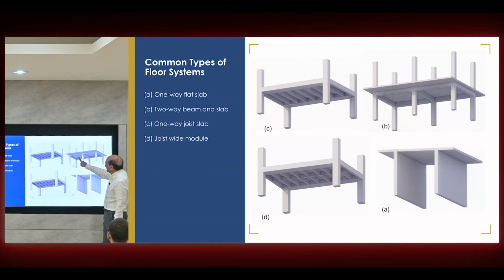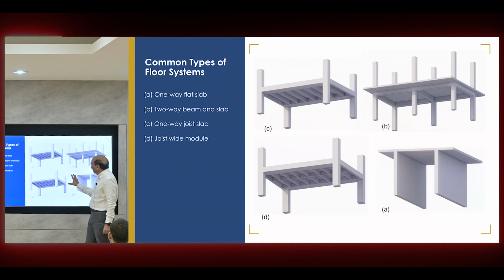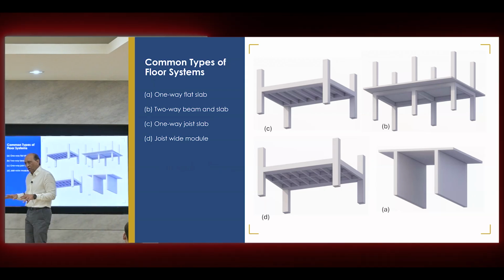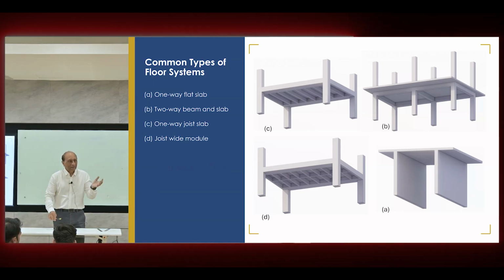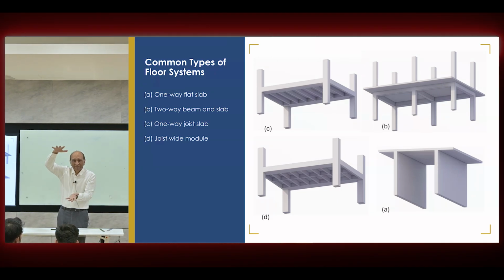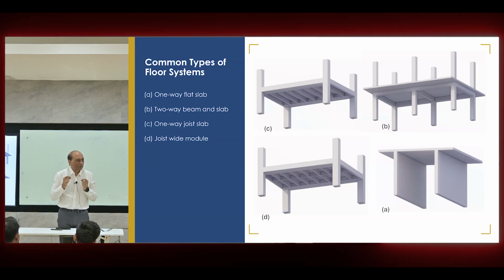We have slabs and beams and columns, and we have subdivisions further, and then we have subdivisions either way. So these systems were common earlier, and they're still common, and the intent behind that was structural thinking. Okay, I have a span, I must get the maximum stiffness with least weight. That was the thinking. Like you said, deflection should be reduced, was the primary thinking behind development of these systems.